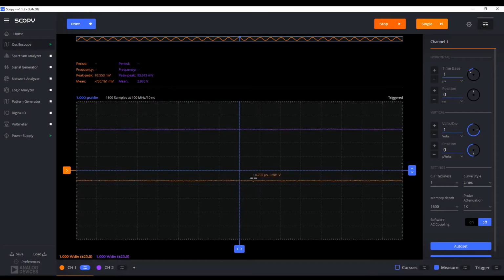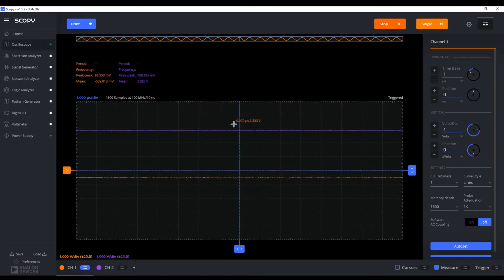And as you can see, while our input voltage is negative, because of this inverting amplifier, our output is now positive. And the reason it's 2.9 is because the output is connected to this bipolar multivibrator, so the output voltage isn't quite what the ideal case would be, which is in the report. But nonetheless, it's still sufficient to power the multivibrator.